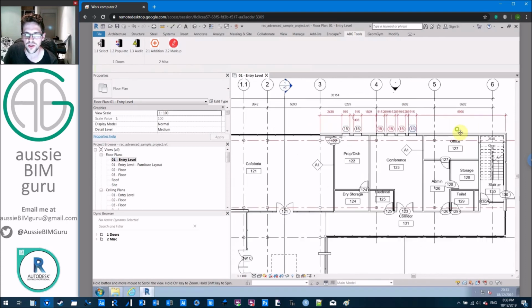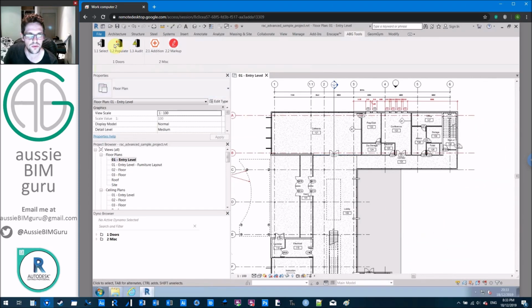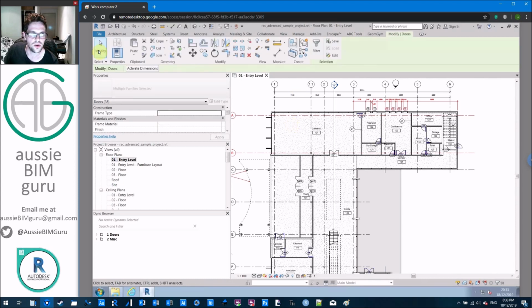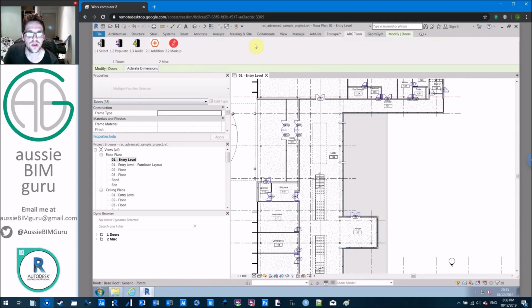What I might do now is just show you some more creative things you can do with it. I guess I'll show you just one other more powerful script I made, which just selects all the doors in the active view. And there you go. You can see I've just picked all my doors in my active view with one button click. So pretty powerful.